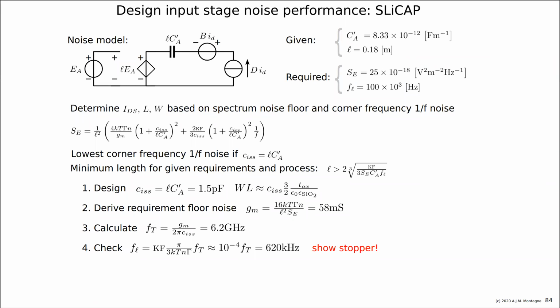And that is very important. It is not based on trying all kinds of things. No, it's really based on fundamental models that we have and say, this is not possible with this process and this antenna. We either need KF to be much smaller, which is a much lower noise process, or we need to have a longer antenna. That's all.